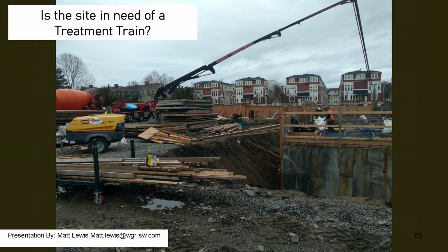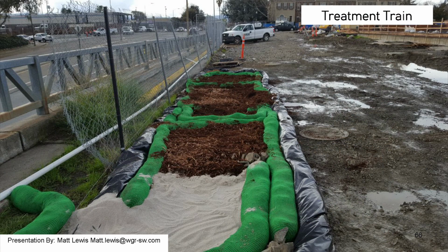So they're constantly pumping out of that pit incredibly sedimentated water. And so this is a treatment train. This is something that usually you don't plan for as a QSD, but if you happen as an inspector to sample and you have NAL exceedances below 6.5, above 8.5, and or above 250 NTUs, this is a pretty good option. It doesn't take a lot of effort.